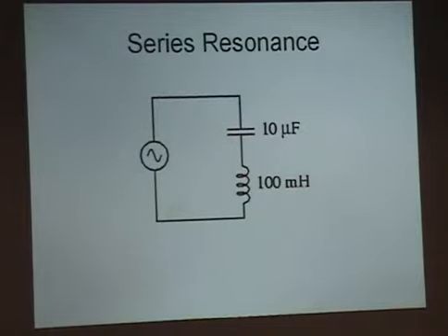Normally we go with tunable capacitors, or in this day and age we have varactors, which are diodes which look like capacitors. But we want to vary one of these so we can then pick what frequency is actually going to come out. So your antenna system sees them all, and you only want to take what the tuner passes out.